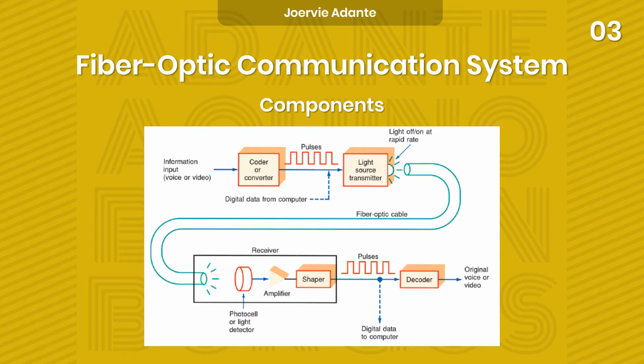Digital pulses are used to flash a powerful light source off and on very rapidly. In simple low-cost short-distance systems, the light source is an LED that emits low-intensity infrared light beams. The source-to-fiber coupler, a mechanical interface, is added before transmitting. This coupler is used to couple the light emitted by the source into the optical fiber cable. Light beam pulses are fed into a fiber optic cable, which is transmitted over long distances.